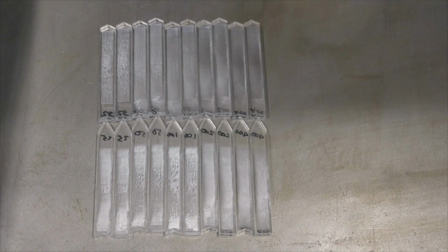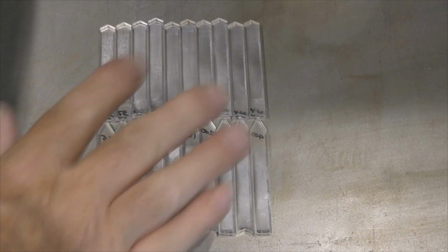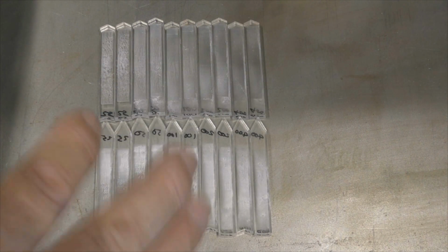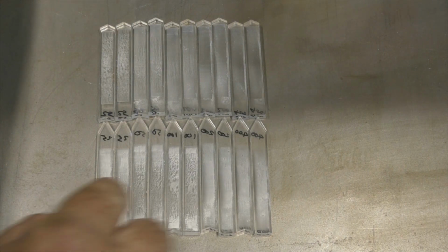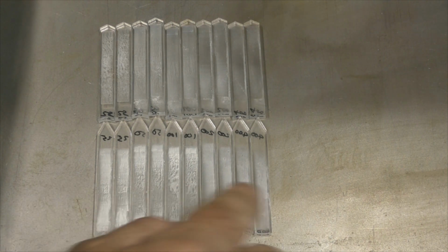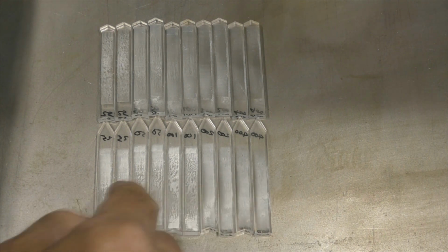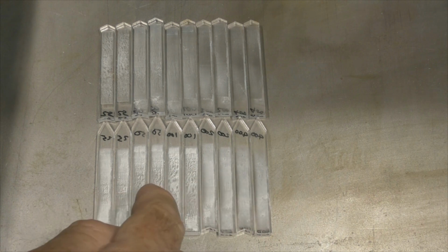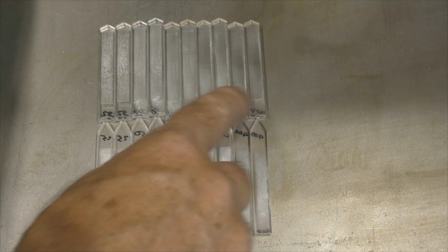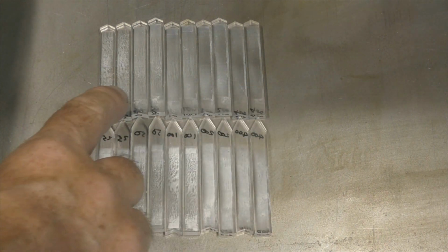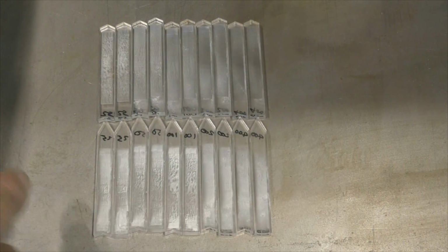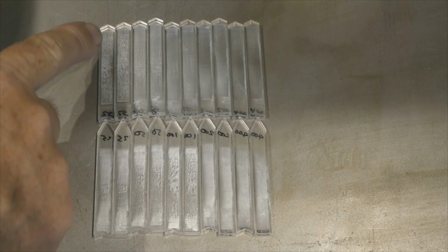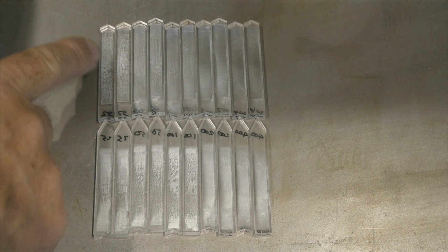Well, here we've got our 20 sets of results, 10 from each machine. I'm just looking at them like this to see just what the physical appearance of them looks like. There is a difference between them. This was done with full air assist, and I've definitely got some blooming on the surface, some condensate. I was using about half air assist on these, and they seem to be much cleaner off of the China Blue machine. But here at 25 millimeters a second, I'm getting a lot of debris in the bottom of the cut.